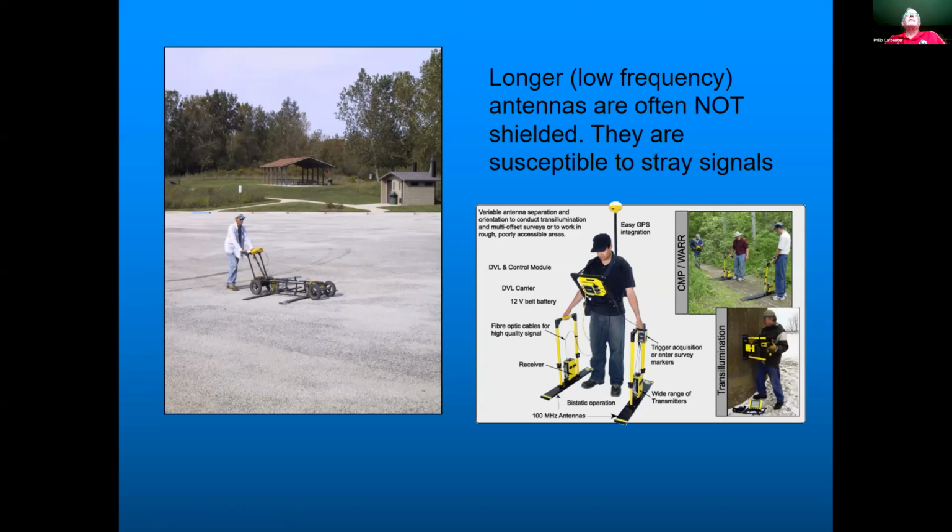If you rent this equipment, it's very important to tell the vendor what you want. I've had students call me in a panic because they got a gigahertz antenna when they didn't specify the frequency, and you can see only about this deep with it. So it's really important to specify the frequency. If you're in a landfill situation, let me know, and I can probably advise you on what frequency to use.